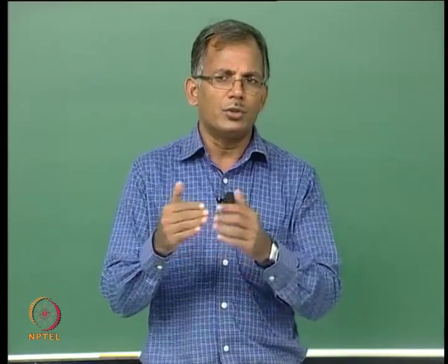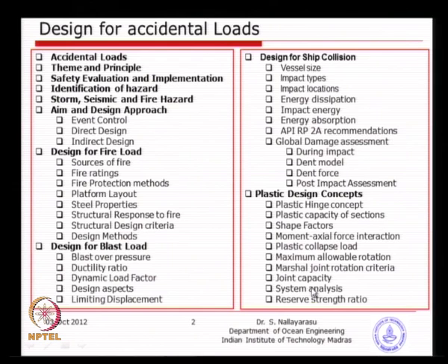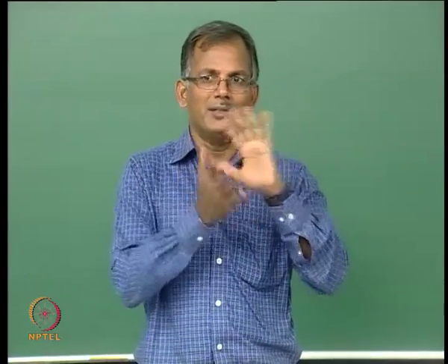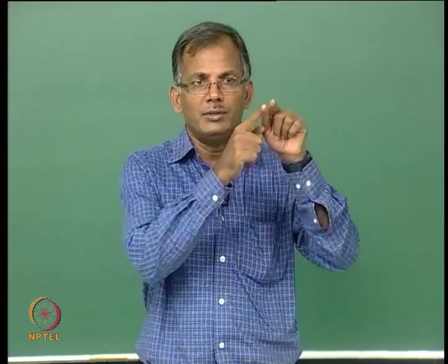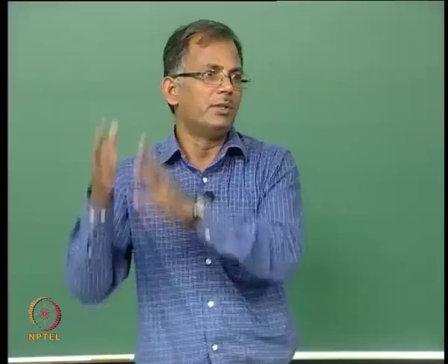In doing so, we will also compare every time we are applying it, for example, when we look at the system analysis, we will look at what we have learned over the last 20-25 classes, where we look at axial stress, axial and bending stress interaction, and we just had a linear interaction, P by PA plus M by MA.